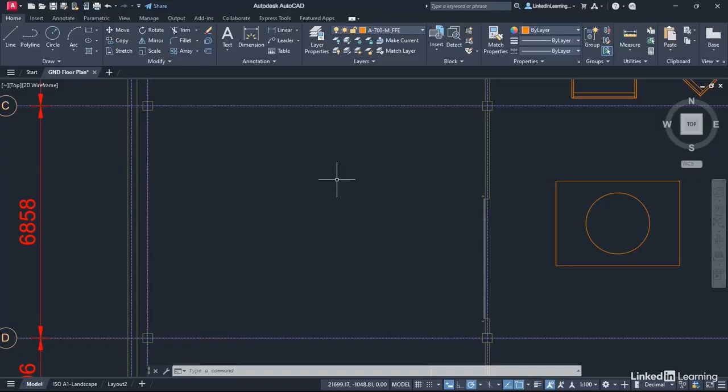And then I'm going to jump back into polar and show you a neat little feature in polar that allows you to use individual angles with your polar tracking. So make sure you're on the FFE layer in the layers panel, over to the draw panel here like so, and we're going to click on polyline this time. We're going to create a 2D polyline. Come into the drawing area, it asks for a start point.